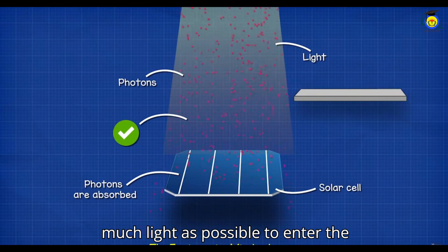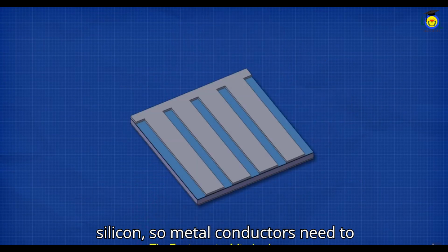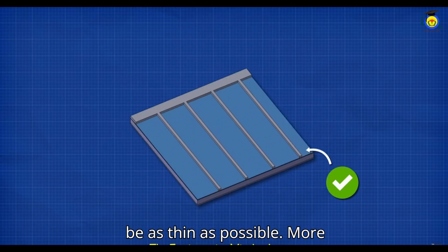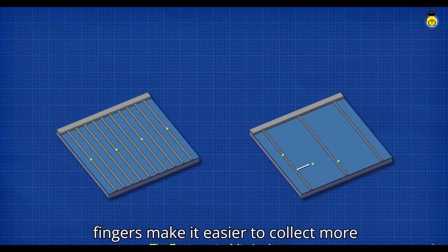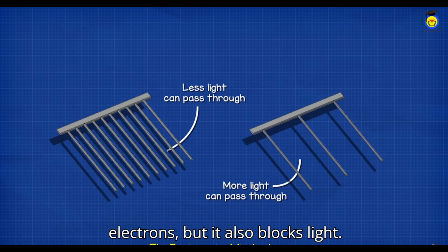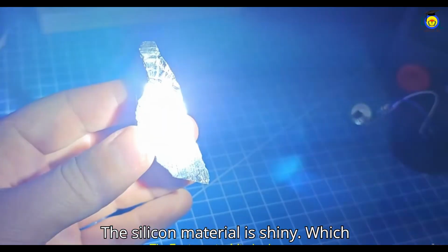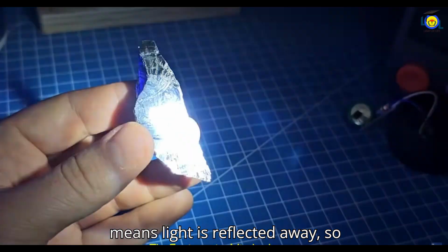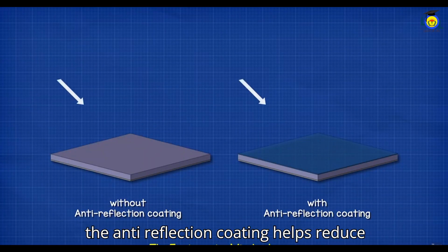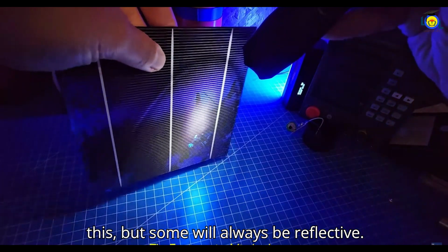We need as much light as possible to enter the silicon, so metal conductors need to be as thin as possible. More fingers make it easier to collect more electrons, but it also blocks light. The silicon material is shiny, which means light is reflected away, so the anti-reflection coating helps reduce this, but some will always be reflective.